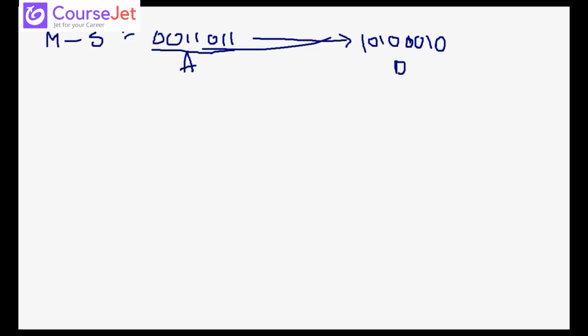Okay. Now first what will happen, first I have to give my clock, right? So when my clock is high, at that time if I give a high to low, this is considered as my start. So this particular thing is considered as my start thing.